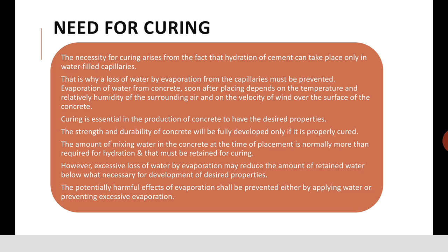Curing is essential in the production of concrete to have the desired properties. Compressive strength and durability of the concrete will be fully developed only if it is properly cured. The amount of mixing water in the concrete at the time of placement is normally more than the requirement for hydration, and that must be retained for the curing.